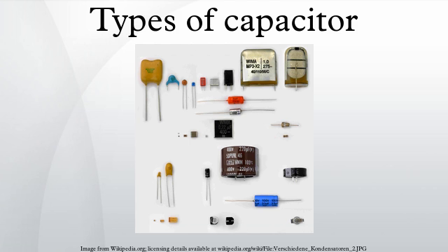As of 2012, the standard storage time for electronic components of 2 years at room temperature, substantiated by the oxidation of the terminals, will be specified for electrolytic capacitors with non-solid electrolytes too. Special series for 125 °C with organic solvents like GBL are specified up to 10 years storage time, ensuring proper electrical behavior of the capacitors without preconditioning.